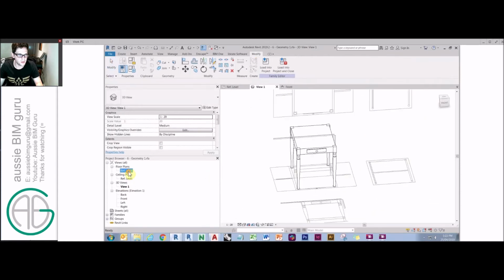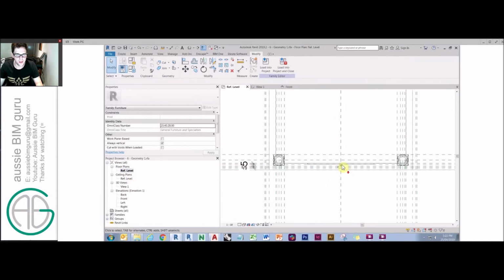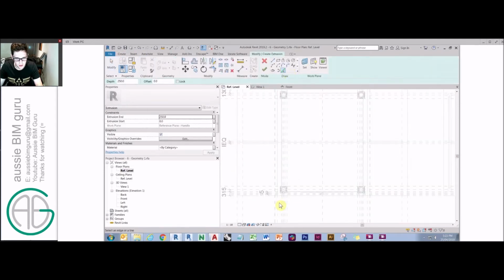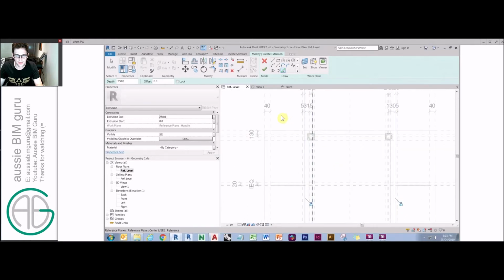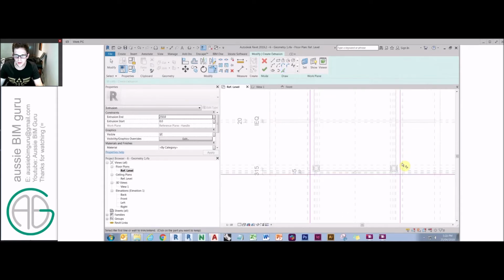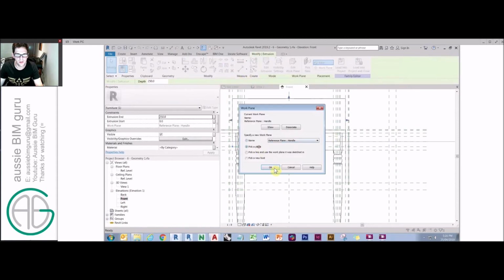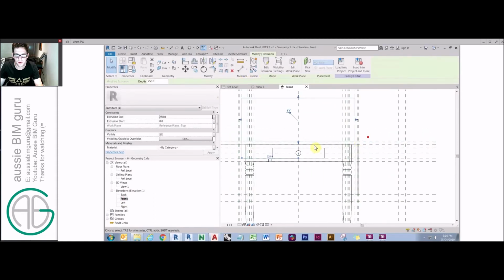So from there we can model up the countertop. The countertop's quite straightforward. I'll just model one and probably skip the other and then come back when it's all together. But basically it's just going to be an extrusion modeled on top. And I've actually gone to the point of saying that the countertop will be made out of two pieces. It'll be made out of its substrate and its laminate, like the actual product is from IKEA as well. Because I prefer families to be as accurate as possible when the information is known.